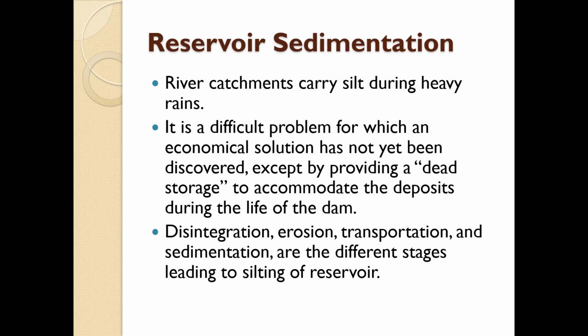For example, Bhakra Nangal Dam has a gross capacity of 9,344 million cubic meters and dead storage of 2,054 million cubic meters. All the outlets fetching water from the reservoir are provided above the dead storage level.